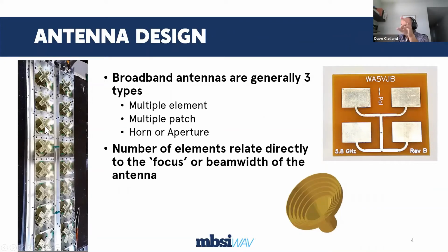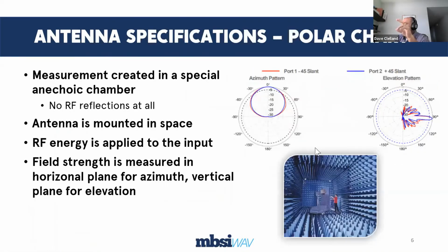If they're in a particular spacing, this value may be 0. If they're altered, the spacing maybe is made a little bit closer, then the differences in the phasing between the arrays will bend this signal down, and so then the main beam can be bent down. Sector antennas that we commonly use in the telecom business can have fixed down tilt of 0, or some manufacturers fix the down tilt at 2 degrees or 4 degrees.